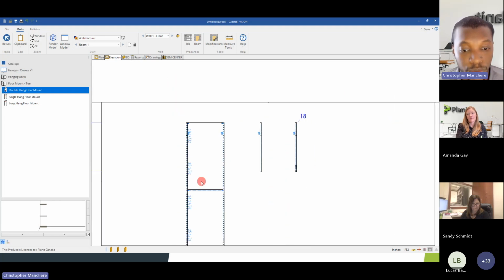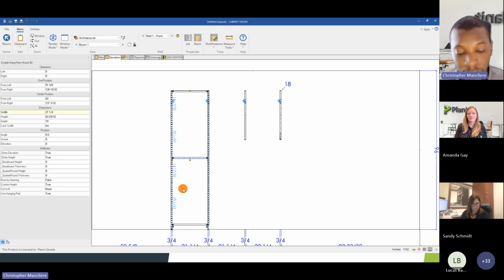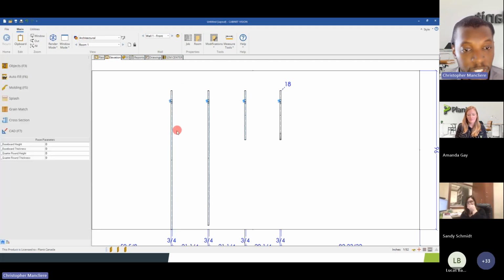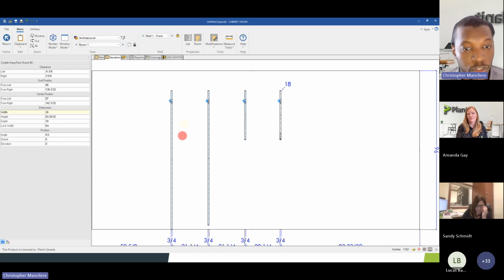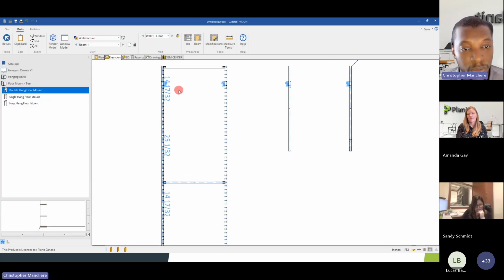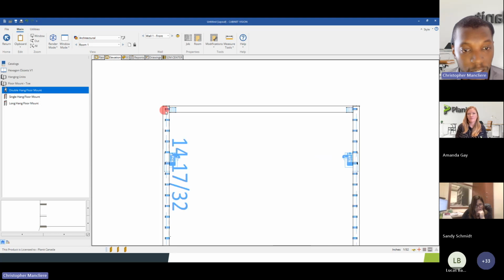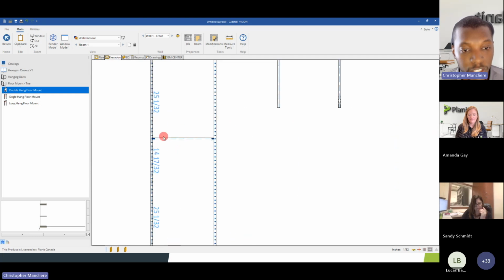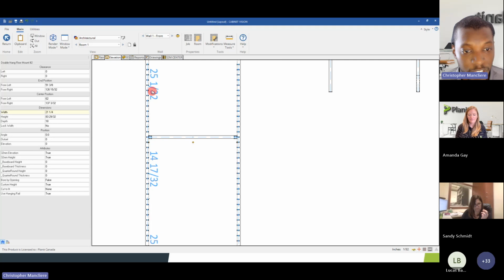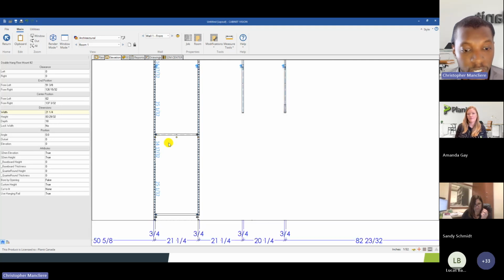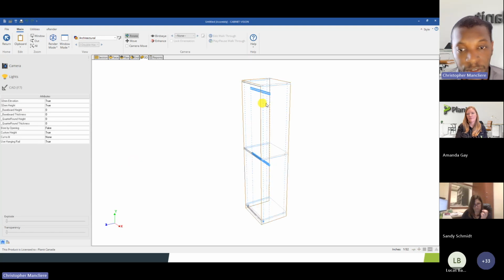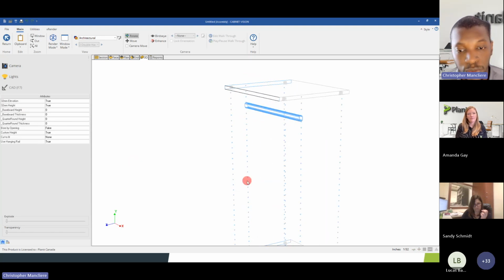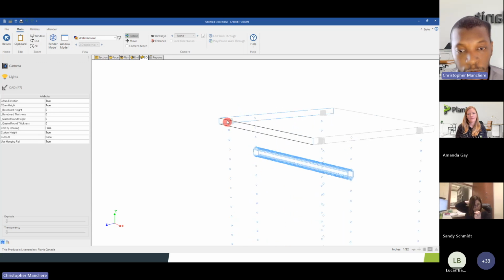And that's very important to note that when you have a closet, if you don't have anything between the panels, nothing will happen because there's no need to create machining. But if you now drag and drop an assembly with some section, the machining will actually be created because the machining comes from the actual section and the opening here. So now if I need a fixed shelf, it means I need to have machining to install this fixed shelf. And then we can even look at the fixed shelf. Right now I have additional drilling just for my rod. I have drilling for my shelf and cam locks.